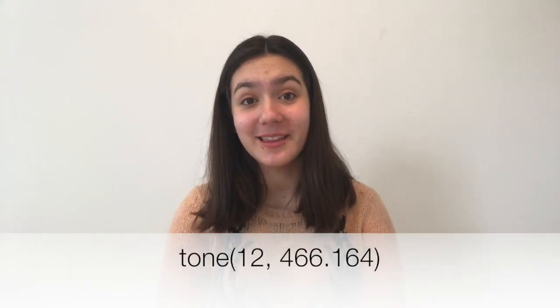The first step is converting musical notes to frequency so the buzzer knows what pitch to play. Referencing the sheet music, I wrote down all of the musical notes played in the chorus of Life on Mars. Using a chart I found online, I paired the musical notes with their corresponding frequencies. The first musical note in the melody is B-flat 4, which sounds like this. The corresponding frequency of B-flat 4 is 466.164 Hz. So to get the buzzer to play B-flat 4, the code looked like this.